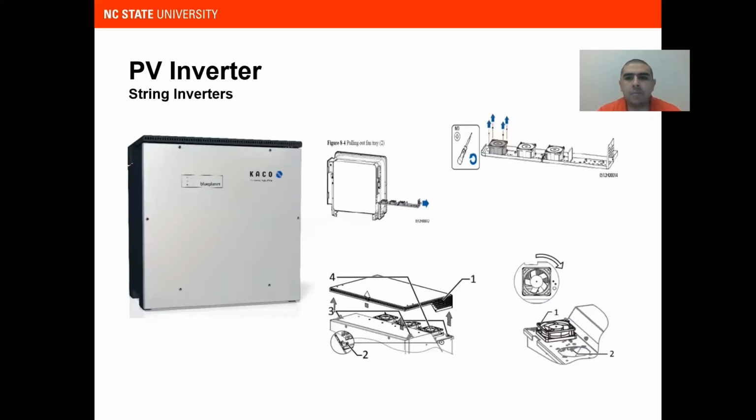The string inverter has the same function, but as you can see here, the string inverter has fewer components. Also in the market, you are going to see that string inverter technology is moving toward plug and play. You don't need a lot of technical expertise, compared with central inverters, to change some modules. For example, this is the cooling system of the string inverter based on fans, and it's very easy to install and remove if something happens with the fan.